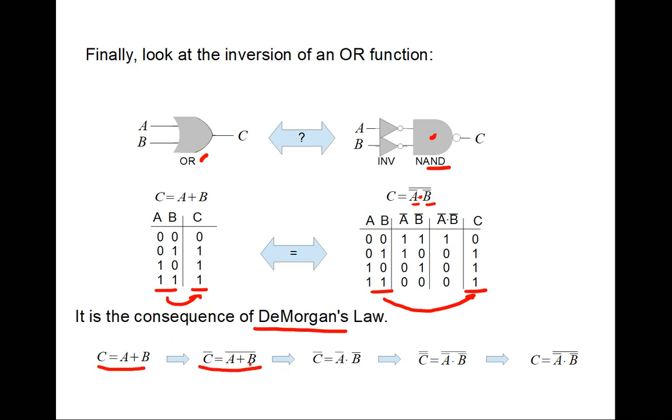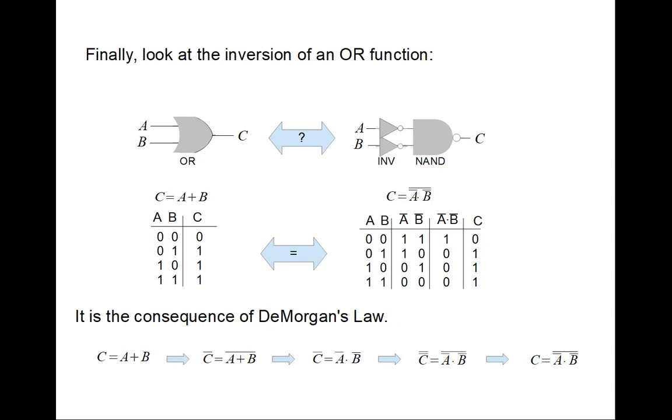All we do is we invert the whole thing, because if this holds, then the inverse must hold. Now we use De Morgan's law. We took the NOT of A plus B and we just said it's A-not AND B-not, and there's an AND now, where before it was a plus. And then we would invert it again, and then we would get the result we had here. Now, is this important for you? Probably not, but I just wanted to expose you to the fact that in Boolean algebra, there are many different rules, and there are ways that we can cleverly convert one problem to another problem, just like algebra.